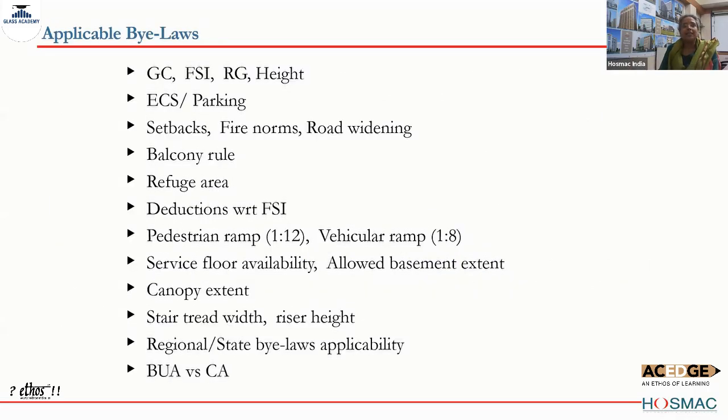Again, these are the rules which will help us build the hospital. GC is ground coverage. FSI is floor space index. It is equivalent to FAR. There is no difference. This is just a difference of terminology. The RG is recreational ground: how much, and what percentage, of recreational ground we are supposed to leave on a site.